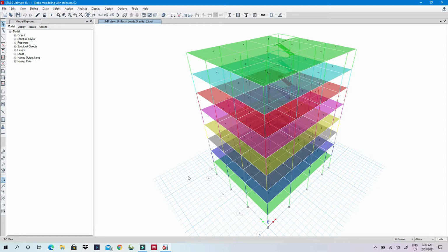So what you did is you increased the section of the column, so that is more concrete, and also because it is a bigger section, it will need a lot of reinforcement to hold it. So you will increase concrete, and you will also have increased the reinforcement needed for the structure.